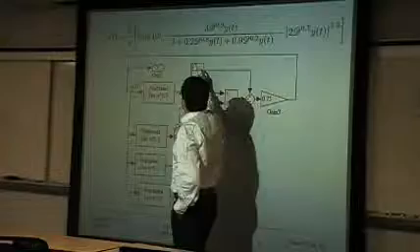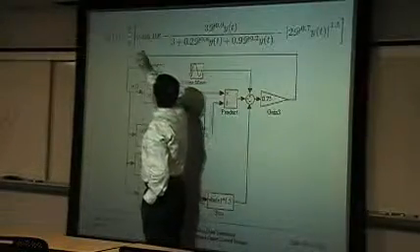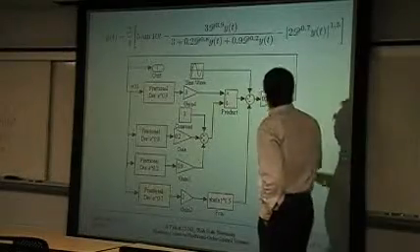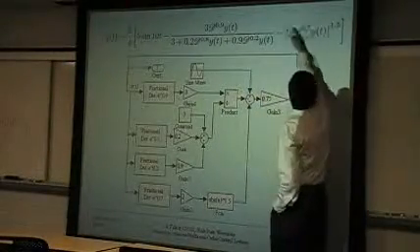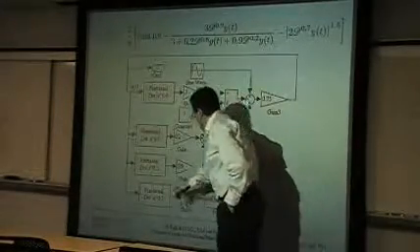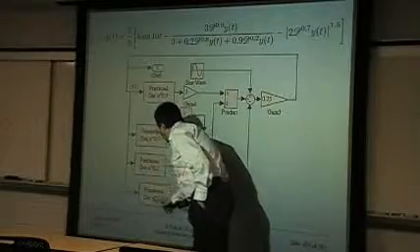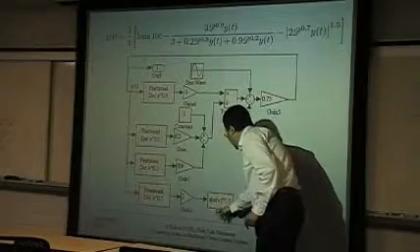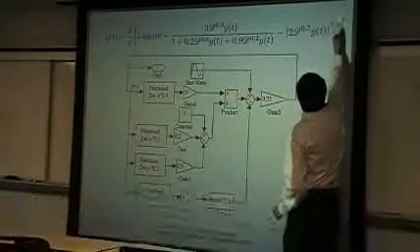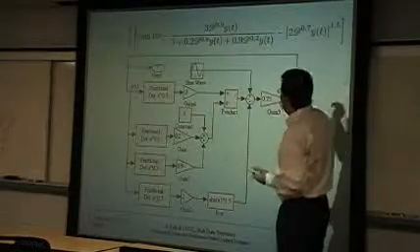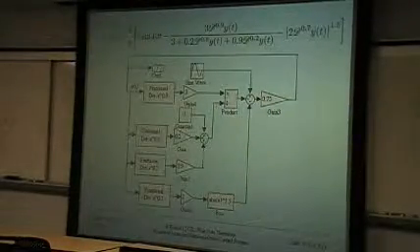And this is the input signal. We can assign that the gain, the amplitude, is 5 and the frequency is 10. And for this part, we have to construct the inner part first. 2 times the 0.7 order derivative of y, and then we can use the ABS block, and then the power is 1.5. So this is a description of the original system, and we can use this description to perform simulation.